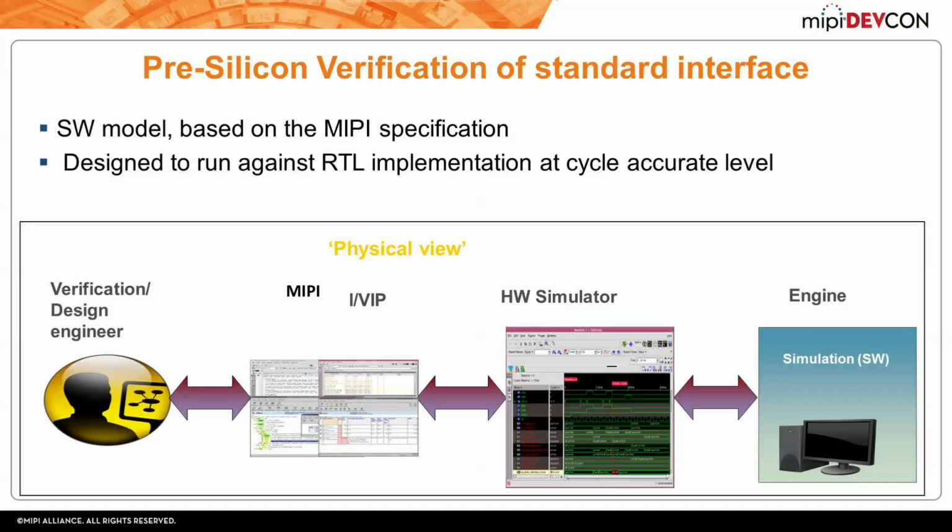It's designed to run against any RTL on a cycle accurate level, and basically the verification engineer connects with a simulator to the device under test, runs a certain test, and then we can debug the results.